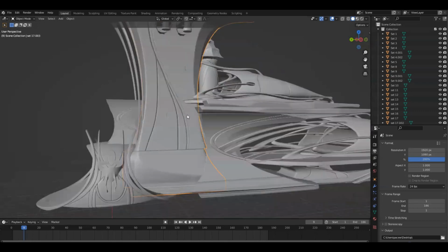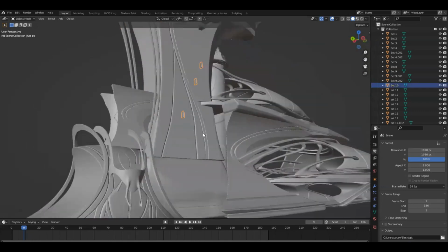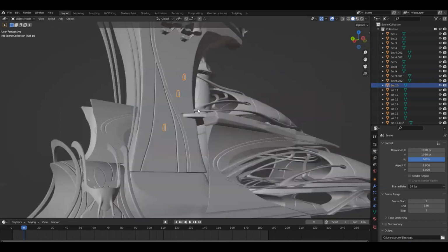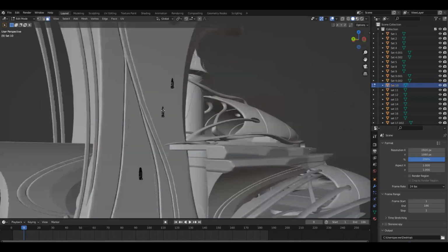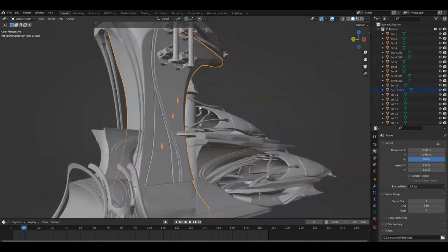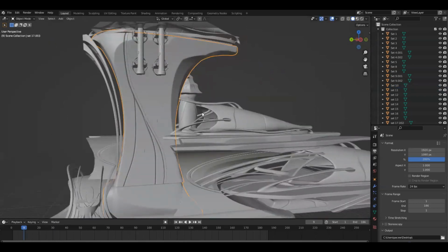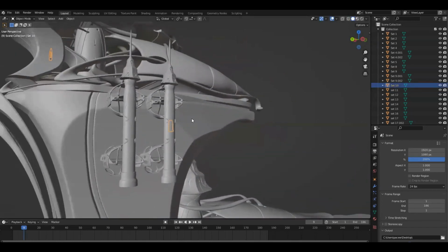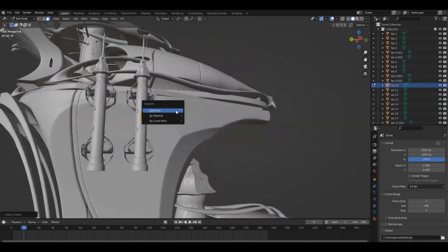And I just wanted to show you, remember we added those windows completely separately, so they ended up exporting separately. So I will probably try and add those right now, separate them with the L key, and just join them with the segments that make sense with Control J. Just so that when we are selecting and duplicating things around, it's not going to be so confusing.